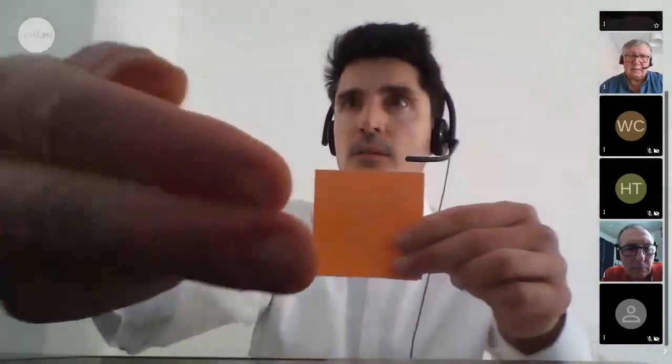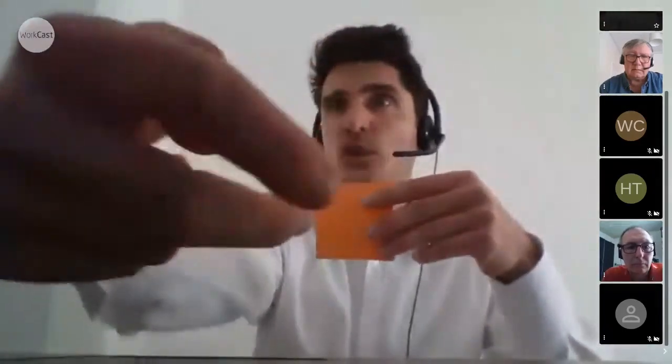Depending on how far you are and how big the object is, you have a field of view. So first it depends on your target. Then the second is the emitter. You will have the emitter to send the light to hit the target, so the emitter you choose needs to have a certain field of view to emit the light. Then the receiver as well will have a matching field of view so that it can receive.